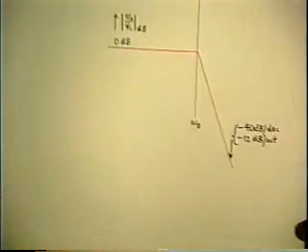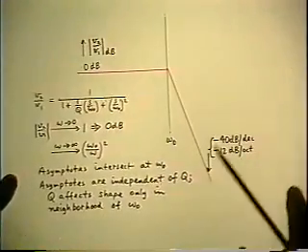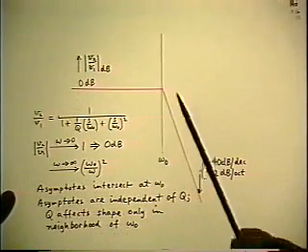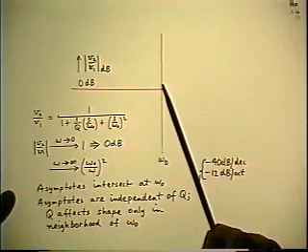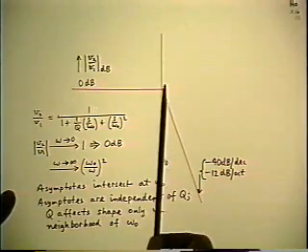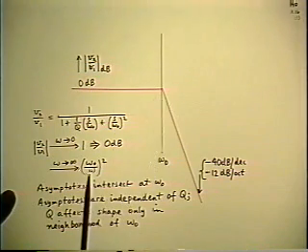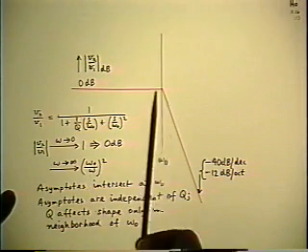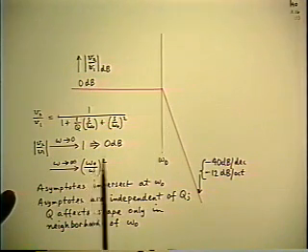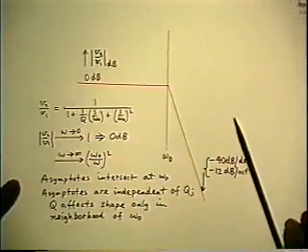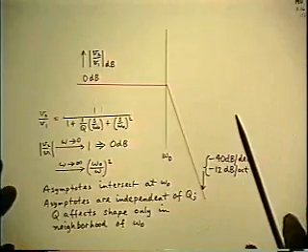So the asymptotes now look like that. Here's the 0 dB zero-frequency one, here's the minus 40 dB infinite-frequency one, and if you extrapolate them to where they intersect, they again intersect at the corner frequency, because that's where both asymptotes have the same value, namely unity.